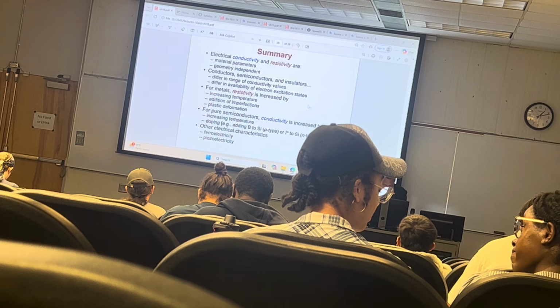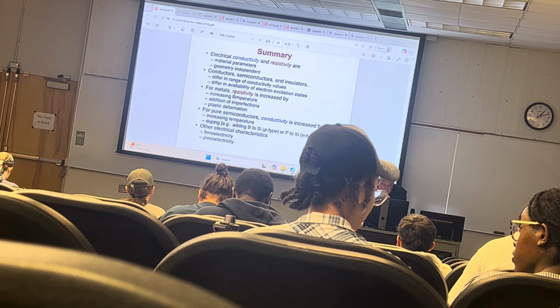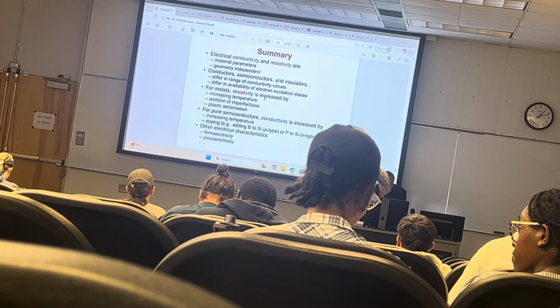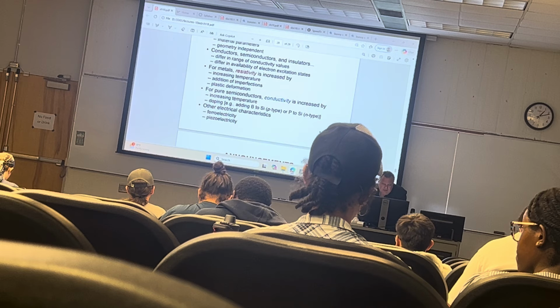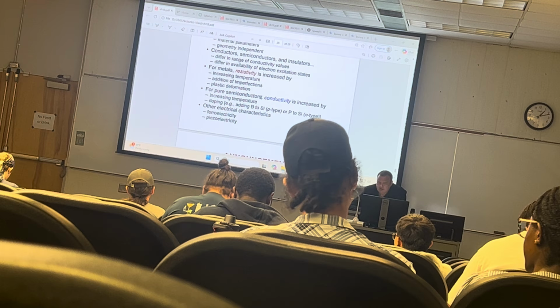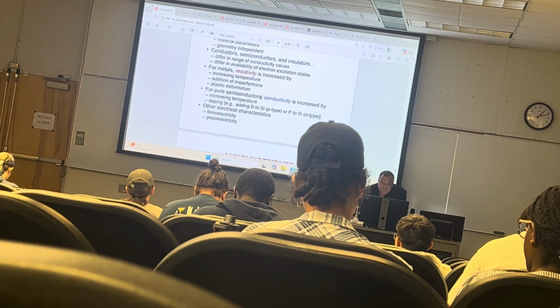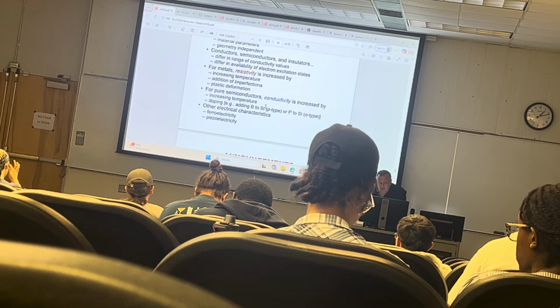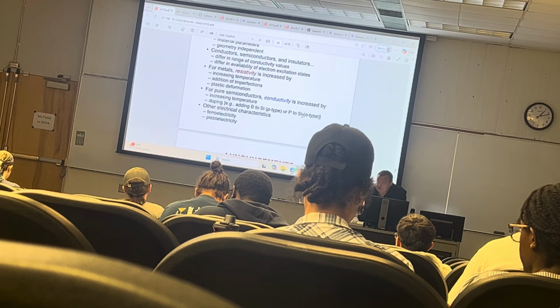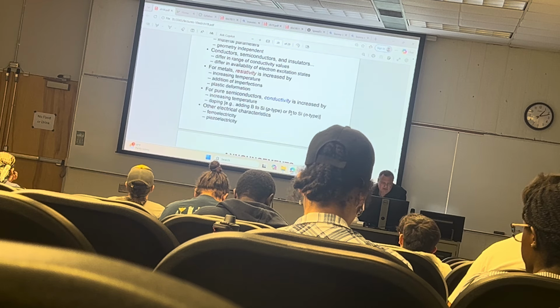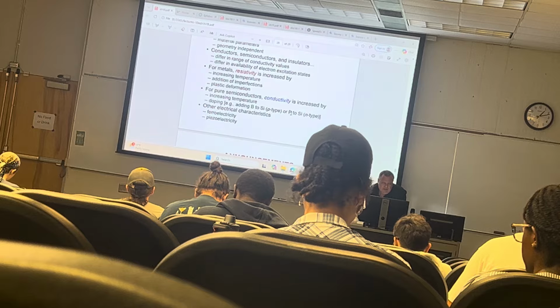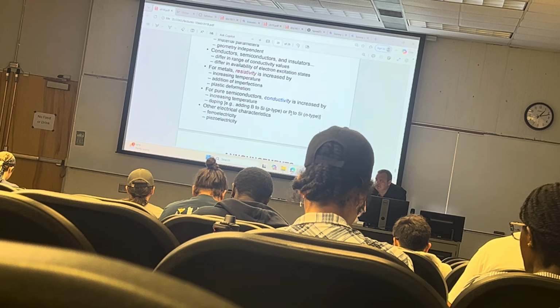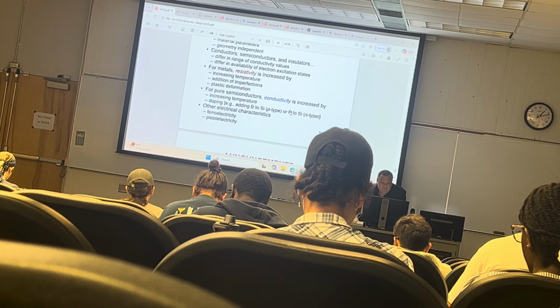We looked at the effects of temperature, defects, and plastic deformation on resistivity. Then we looked at pure semiconductors, and talked about doping with boron or phosphorus to make p-type versus n-type semiconductors. And we just touched on other electrical effects such as ferroelectricity and piezoelectricity.